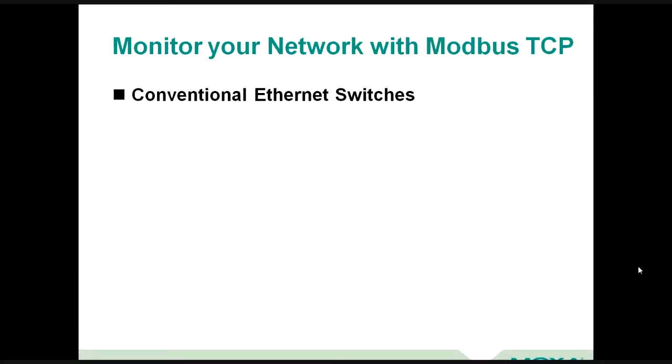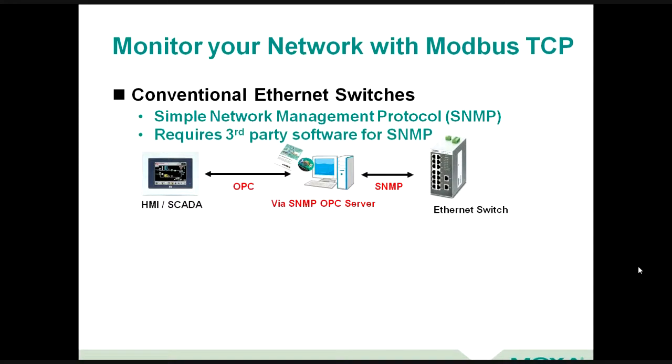And then lastly here, and we'll open up to questions on this. As you're planning your network projects, don't forget about the Ethernet infrastructure as well. I know one of the challenges we found is that oftentimes customers such as yourself are thinking about the end devices and forget about how to instrument the network architecture. If you're using Ethernet switches, hopefully you're selecting managed switches, which give you ways to look at performance and availability of your networks. It's not easy to take a traditional Ethernet switch that only supports simple network management protocol and get that into your system.